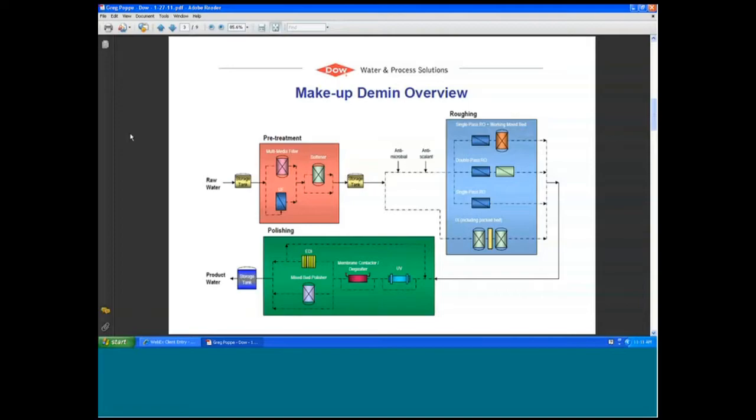And so the roughing step, we have to admit, over time, reverse osmosis technology has grown very rapidly in comparison to ion exchange, and that's great. But for processes where you have a relatively low total dissolved solids level, or maybe there's an extremely large desire to have the highest recovery possible, there's still a very good competitive argument for ion exchange in those systems, and that's really where we're going to focus today.